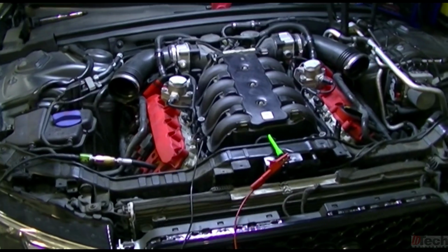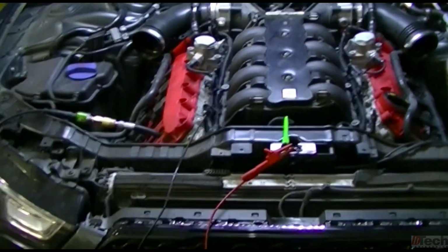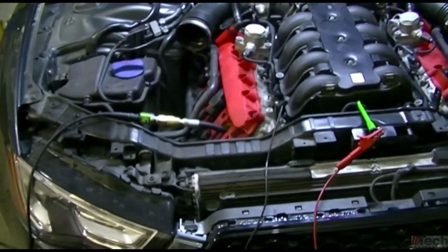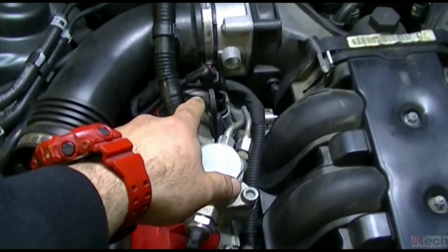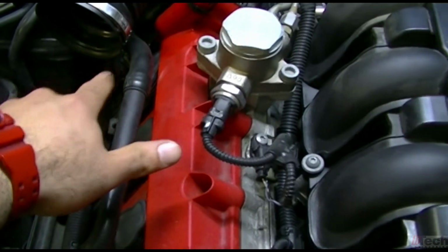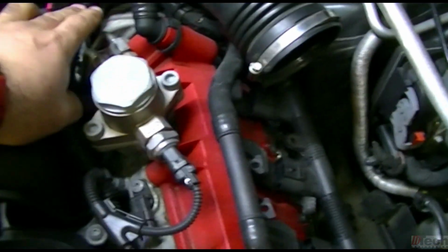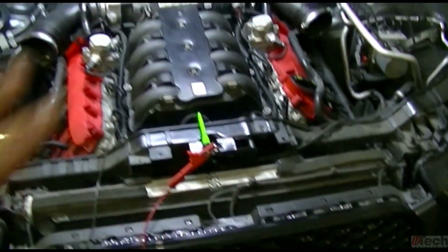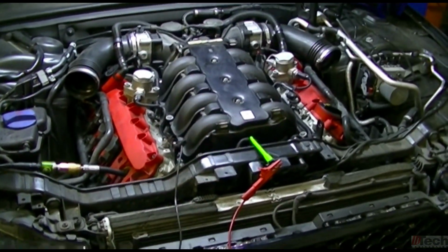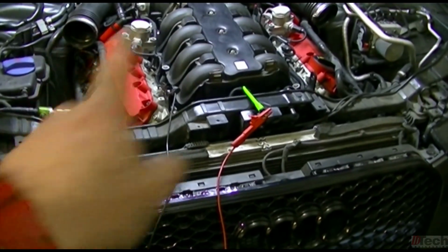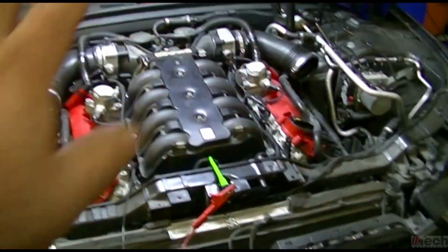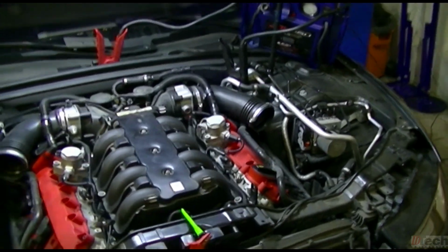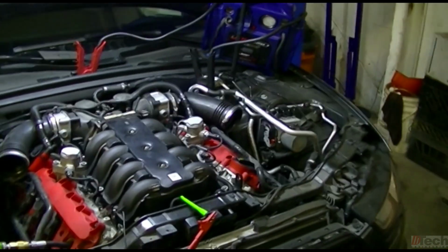Okay, so now I've got everything set up that I want to look at. In cylinder number 1, the transducer. Then I've got all the other ones down there, all the variable solenoids unplugged, and obviously I'm going to be doing a lot of cranking since I'm testing both banks. I want to try to keep the voltage and amperage consistent and high.